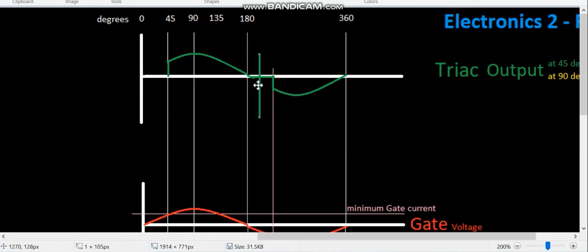And so I can control the amount of power there, because normally, with DC motors, we take the DC supply and we decrease the amplitude of the DC, and we can therefore control the speed of the motor. But with the AC here, what we're actually doing is decreasing the amount of time that the waveform is allowed to conduct, and we end up getting less power, but without having to reduce the amplitude. But when you calculate your values for RMS, you're going to see that if I'm at a 90-degree firing angle, I'm going to have 50% of my power, right? So another way of doing it.